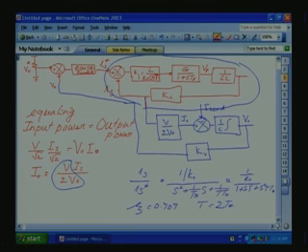These are frequencies multiple, these are the square of frequencies. So, this current loop in this closed loop should act very fast compared to our voltage loop. That means the frequency response of this one is much higher compared to the voltage loop for fast action. Now we have to design the voltage loop.